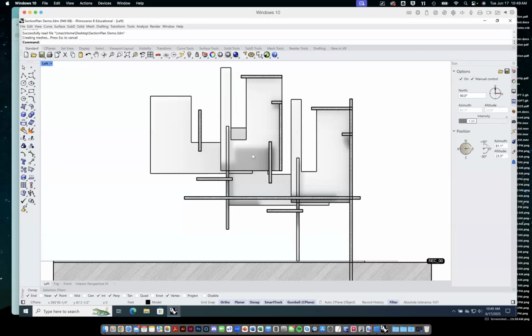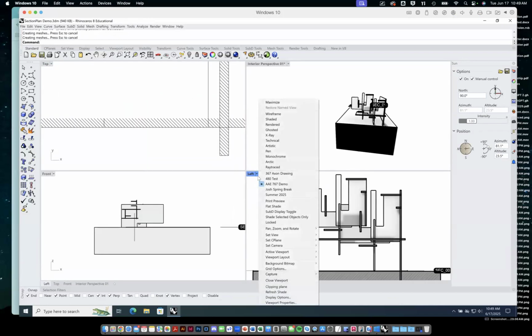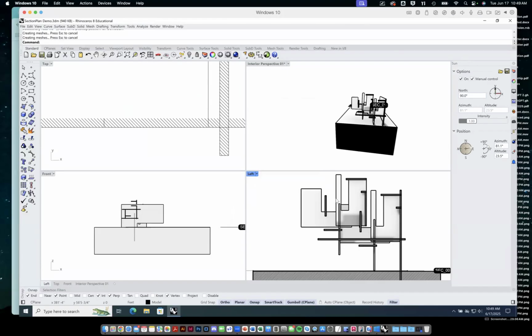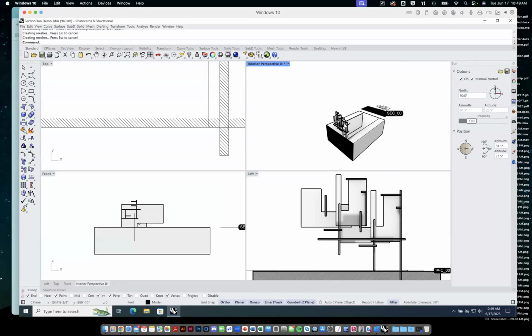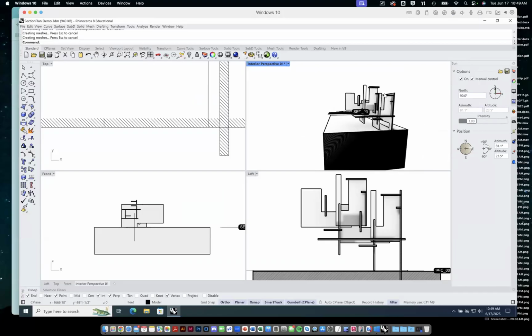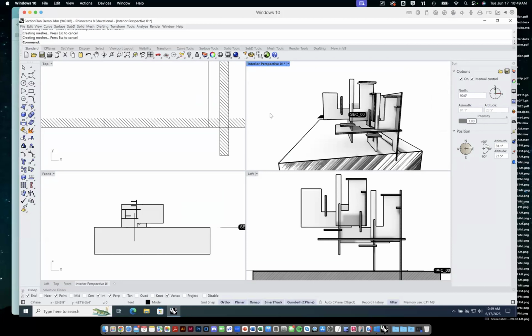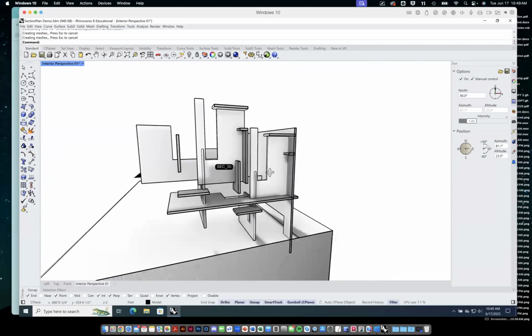Let's see here. All right. Interestingly, this is usually the right view, and because of the direction I was cutting the section, I changed it to the left view, so I could see the section cut and then see what's beyond or inside. But here you can see the same model, cut in section and clipped so that we can see inside. So here's another way of showing that section drawing. This is called a section perspective. We're just in perspective mode, and then we're clipping part of the building away and it disappears so we can see inside as a cross section.